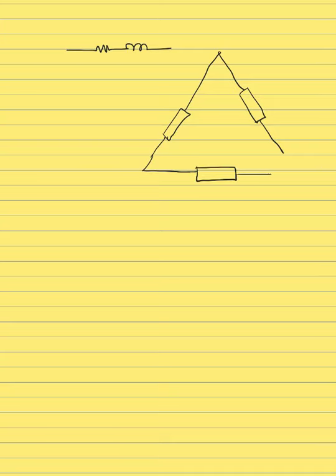Now what we have is, here were the line currents flowing, and this time I'm skipping drawing the source side. I'll only draw the load side, because whatever I needed from the source side, I have. I need to draw back the load in the delta form. Why? Because I am asked to calculate some variables in the delta, which I cannot see once I change it to wye. That's why I'm drawing the load in the delta form again.